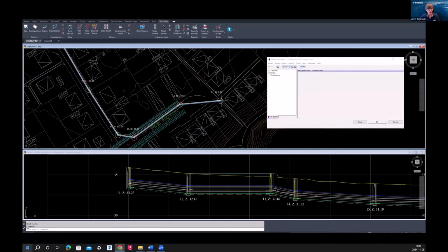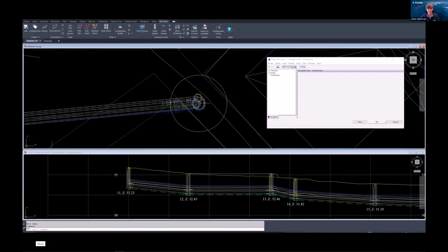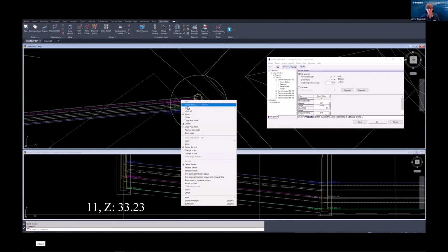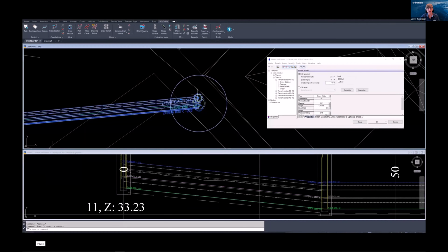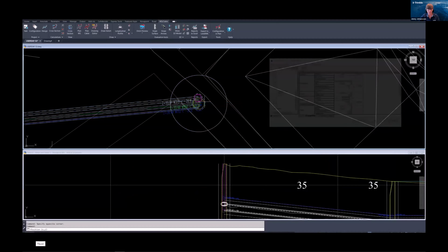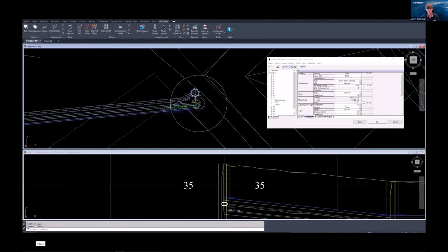Now let's see the first node that we have made here. And as we can see, we have 3 connections over here, and they are all in conflict with one another. Now I need to move connections. And first, before moving the manhole that we have over here, I will insert a vertex on the pipe to make it possible to bend there. So insert a horizontal vertex, and after that, I can just right-click the manhole and move it to the desired position. And the vertex will function as a breakpoint for this pipe.